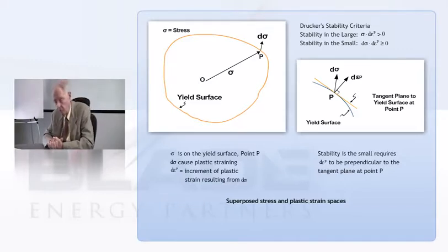So what would happen when you come up to this surface now is that d sigma won't go out. It comes back in because the yield surface collapses on you. So you could hardly expect to analyze this using equations that are appropriate for a stable material, according to what's sometimes called Drucker's hypothesis.